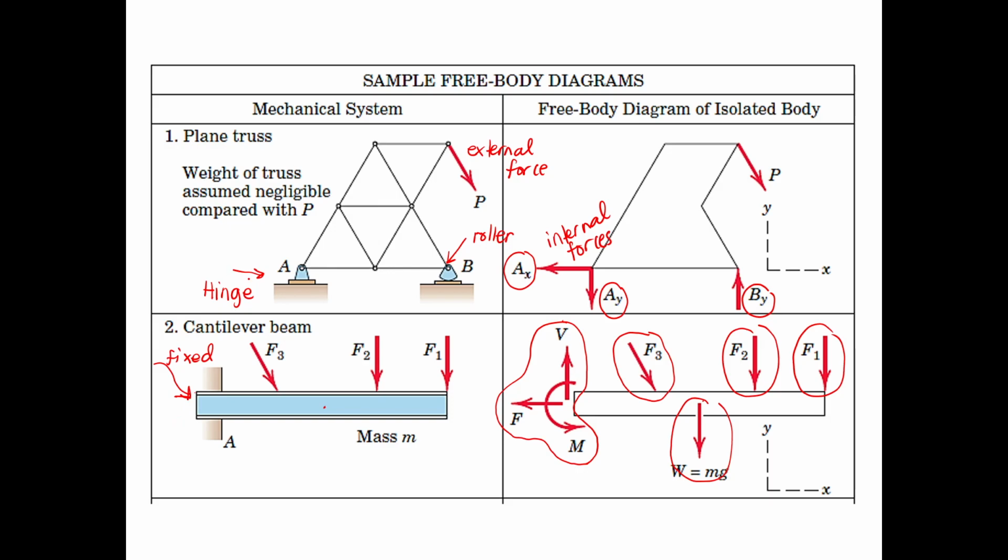And then usually if you have fixed supports, we're going to have three types of reaction forces. One is vertical reaction, horizontal reaction, and the moment. There is a moment because if you imagine this as a diving board, it bends, right? So there's a moment created there.